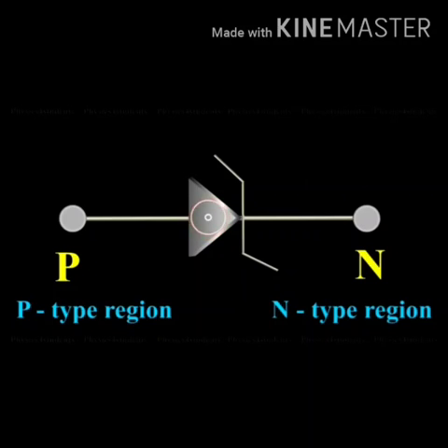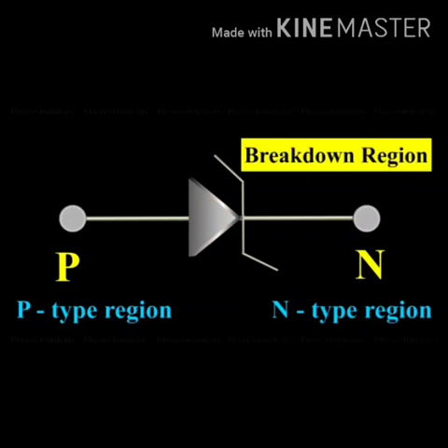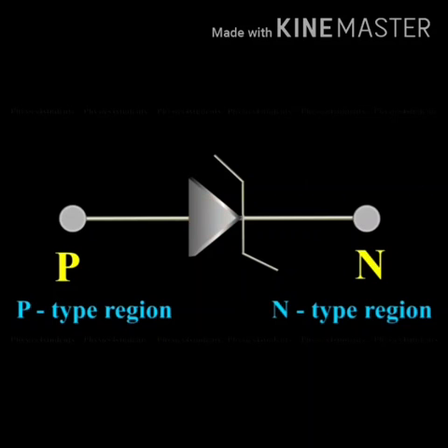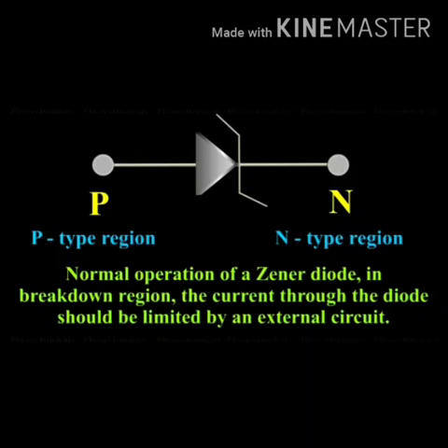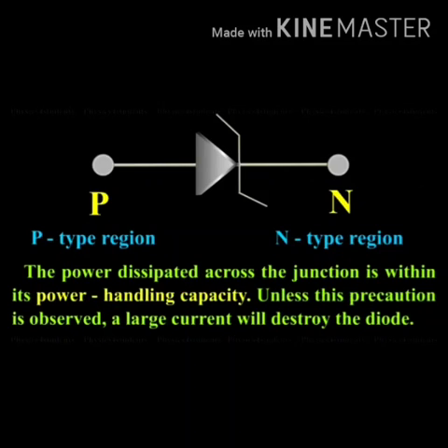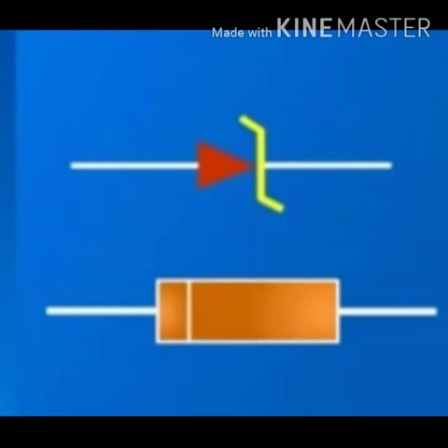The doping level of the silicon diode can be varied to have a wide range of breakdown voltage from 2 volt to over 1000 volt. Zener breakdown occurs due to the breaking of covalent bonds by the strong electric field set up in the depletion region by the reverse voltage. It produces an extremely large number of electrons and holes which constitute the reverse saturation current. The current is limited by both external resistance and power dissipation of the diode.